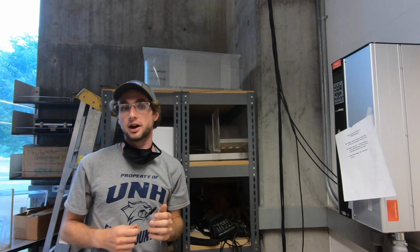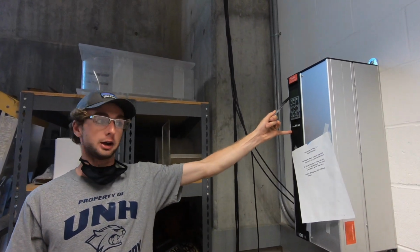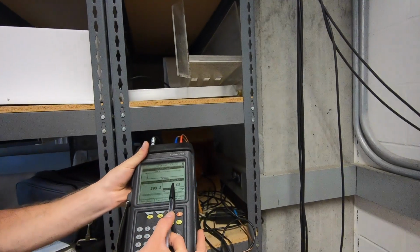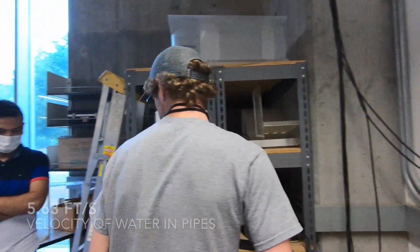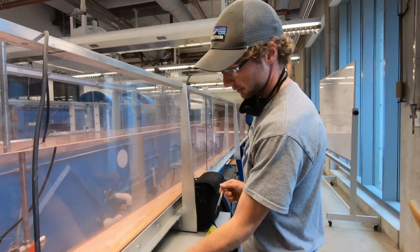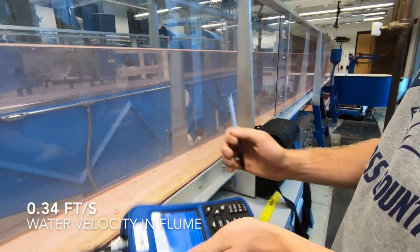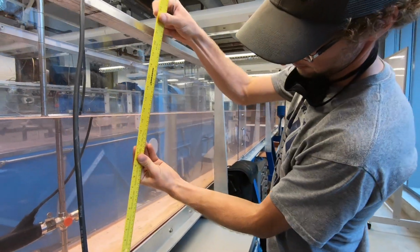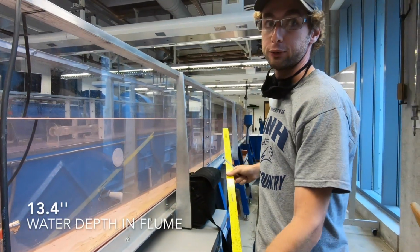All right, we're now on trial number 5, part 1 of lab 3. The pump is currently running at 39% power. The velocity in the pipes is 5.63 feet per second. The Marsh-McBurney flow meter is currently reading 0.34 feet per second at a depth of approximately 13.4 inches.